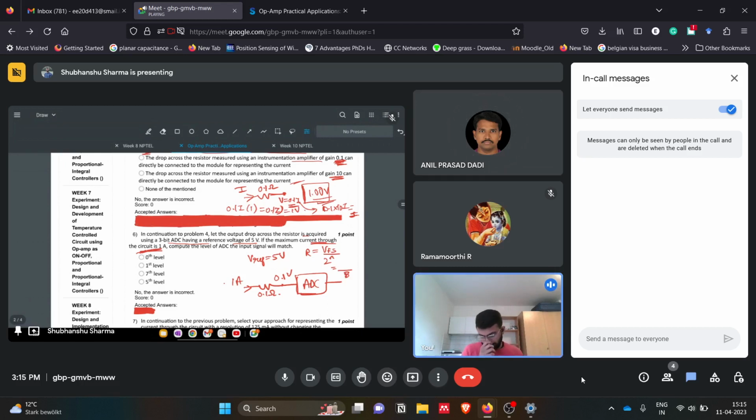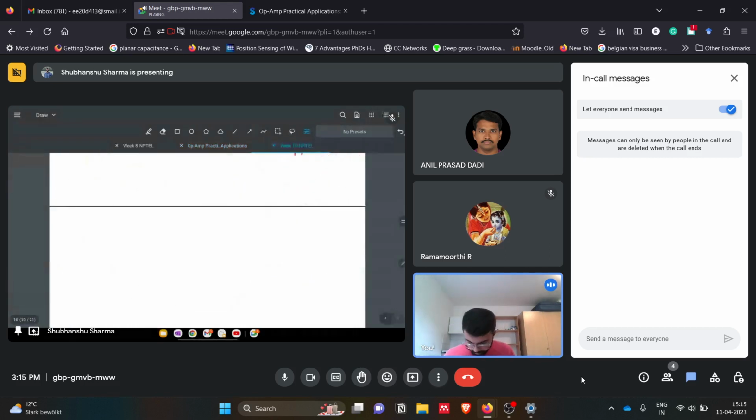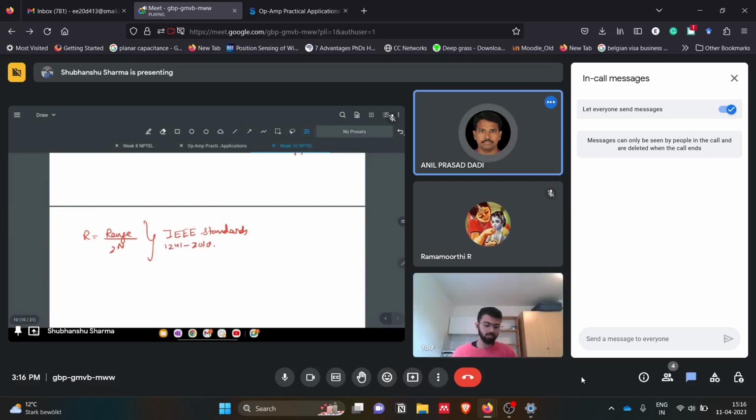Actually, I also thought about why it is like that. There is an IEEE standard, I will write it here. We take resolution as range divided by 2 to the power n. This is decided by the IEEE standard 1241, you can check it.